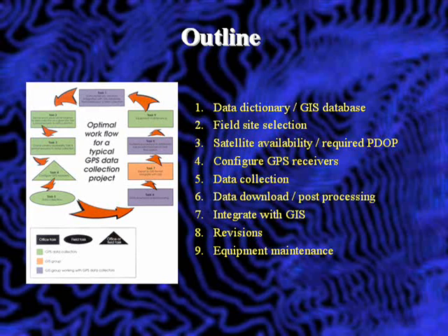One more thing, and that is specifically to ArcPad, and that's more of a file management hint. In ArcPad, all your forms, basically the data dictionary we talked about in the beginning, are associated to shapefiles. So what you'll do, and we'll do that in the next couple of days, is create an empty shapefile and associate that form with that shapefile.